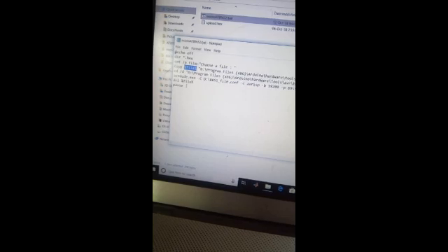The hex file is copied, then after that it will change directory to that AVRDUDE folder location, and then we run AVRDUDE with that flash file, and after uploading it will delete that file in that AVR folder location, then pause to show that it's done. I will be uploading the same to Google Drive and share the link in the description. Again, to make the work even easier, you can do one more thing that I am going to show.